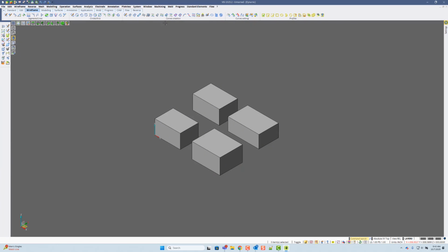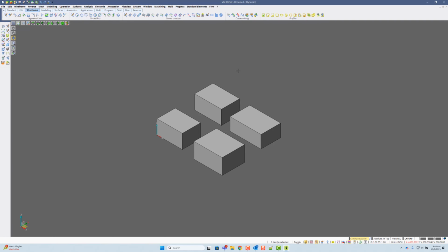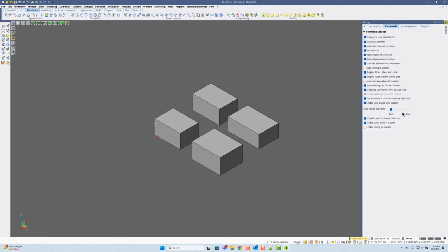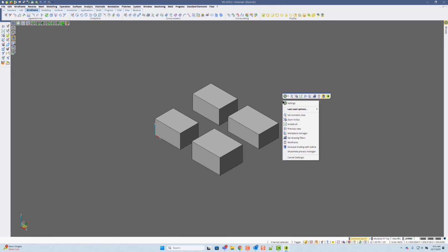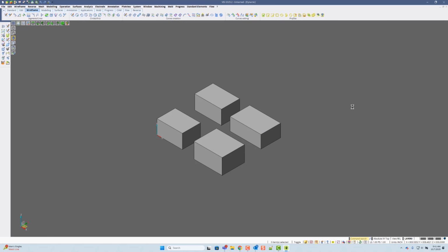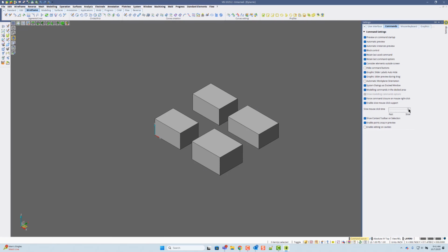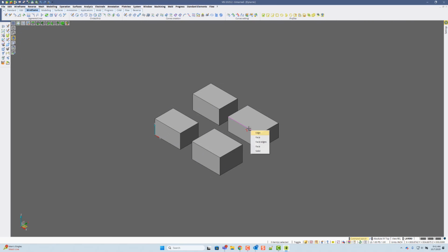The next thing I want to go over is called the slow click slider, slow mouse click. So what this allows is, like, for newer users, if you have it turned to fast and you want to click something, if you hold it for like a second, this little window pops up immediately. And what slow mouse click does is allows it a longer time for that click or that little menu to pop up. So I'm left clicking, hold it for a few more seconds. It takes longer for this little menu to pop up.